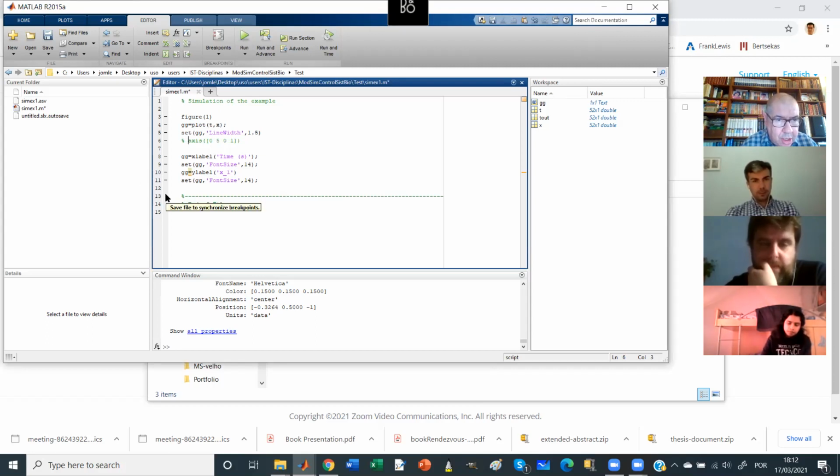I want to do 100 simulations for 100 different values of K. So I don't want to go on changing things by hand, because to do it 100 times I would be tired. It would not be possible. Sometimes you want to do many simulations changing one parameter. So you can have commands to do the simulation controlled from MATLAB. Let's see what you can do.